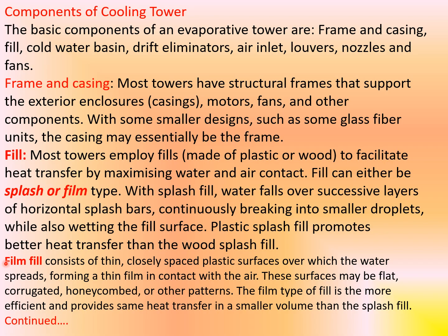The film type fill consists of thin, closely spaced plastic surfaces over which the water spreads, forming a thin film in contact with the air.